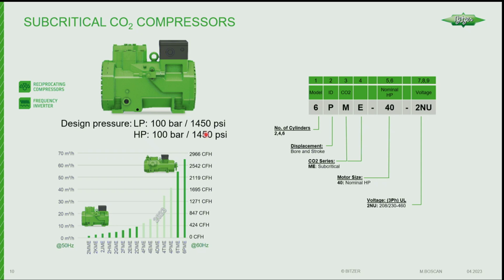What that allows system designers to do is use this compressor and eliminate the backup condensing unit in case of power failure. They can size all their components for a higher bar to make sure that in a power failure you're not going to lose refrigerant. This is more typical on the industrial side or the cold storage side. Supermarket refrigeration doesn't tend to spend the extra money for this feature, because, again, you have to size all your other components to hold that pressure as well, so it becomes rather more expensive and may not be of value to them.